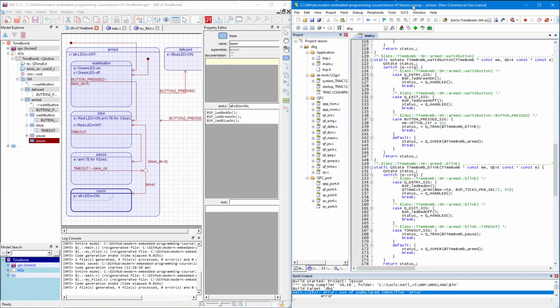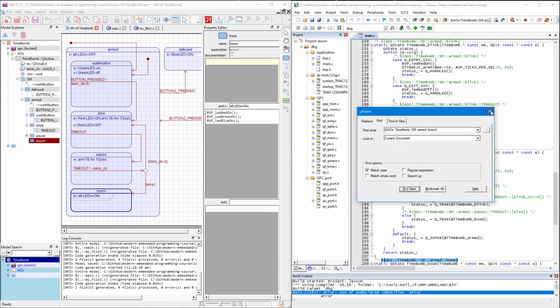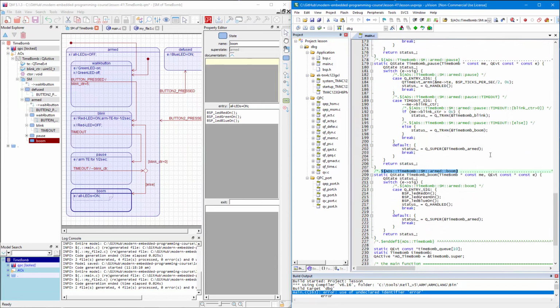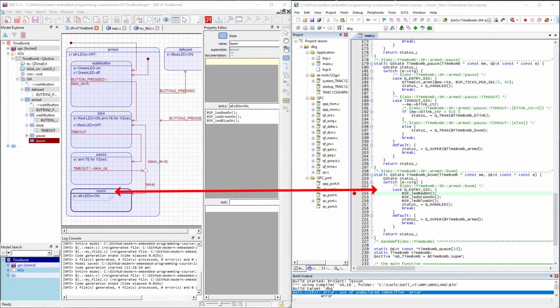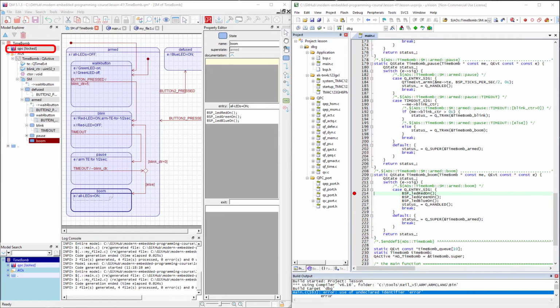to the clipboard. You can then simply search your code for the model link comment. Again, any code editor supports simple text search. After locating the place in the code, you can set your breakpoint and proceed with the standard debugger. Please note that the bidirectional traceability from the model to code and vice versa is the property of the particular optimal state machine implementation that you learned back in lesson 39 and which is used in the QPC framework.